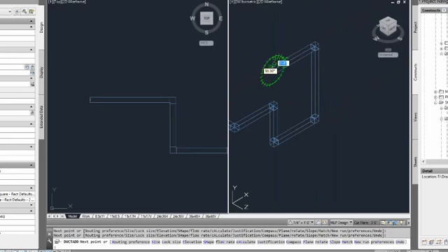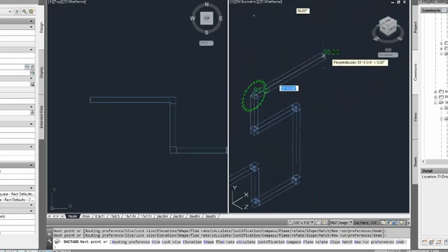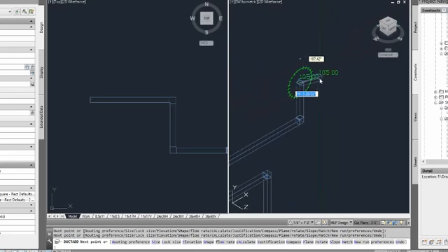So this allows me to be drawing in the top plane, then all of a sudden turn up or turn down into a riser. Now if I hit the P key one last time, it'll turn to the left plane, and that just allows me to draw and turn in that plane also.